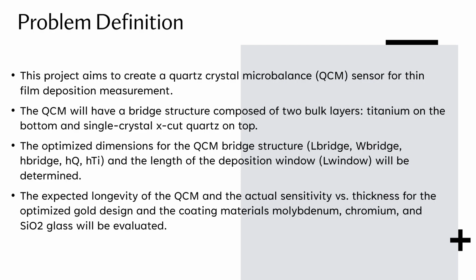The sensitivity of the QCM will be tested for different coating materials, including gold, molybdenum, chromium, and quartz glass to determine the expected longevity and actual sensitivity versus thickness for each material. The goal is to obtain the most extended lifespan possible and push the device sensitivity limit. I primarily focused on writing the report.